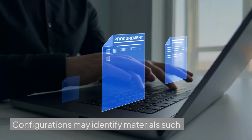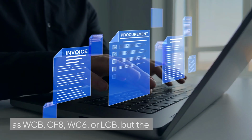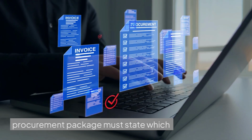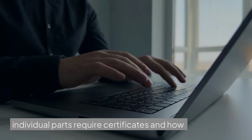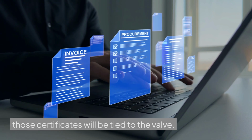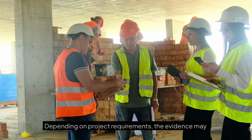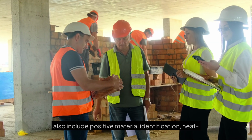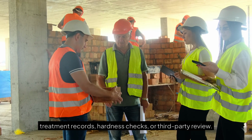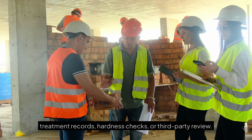Material names are not material evidence. Configurations may identify materials such as WCB, CF8, WC6, or LCB, but the procurement package must state which individual parts require certificates and how those certificates will be tied to the valve. Depending on project requirements, the evidence may also include positive material identification, heat treatment records, hardness checks, or third-party review.